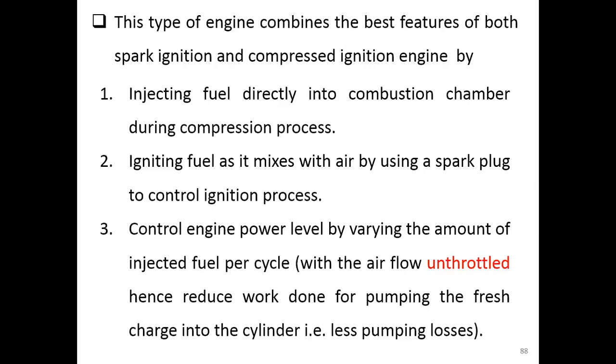So if we let the air flow freely without throttling, the pumping work can be reduced because there is no restriction due to the butterfly valve or the throttle valve. The air can flow freely into the chamber. We only control the amount of injected fuel.